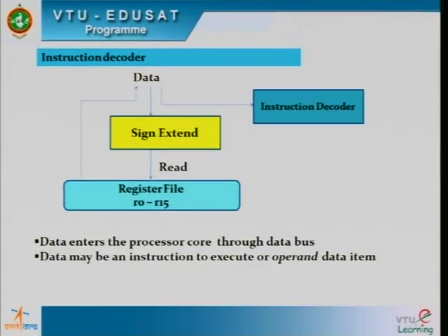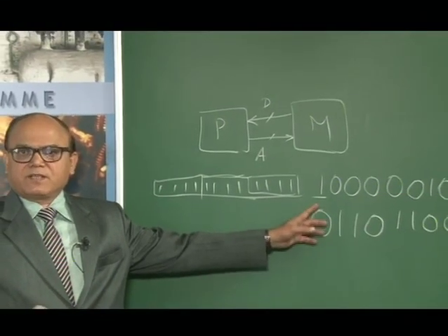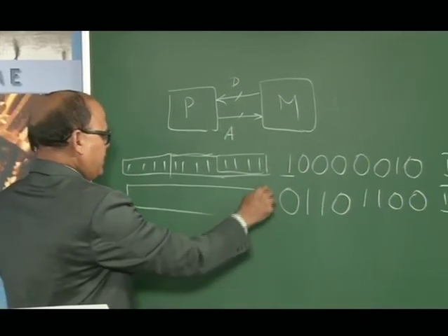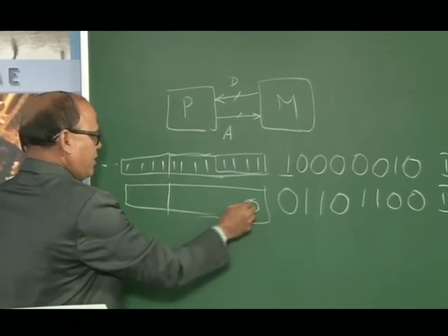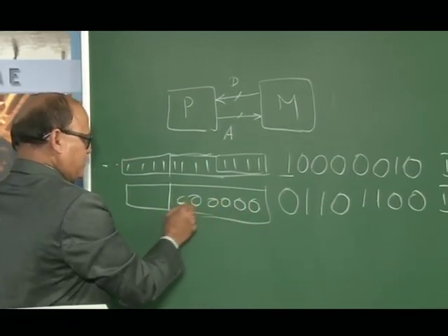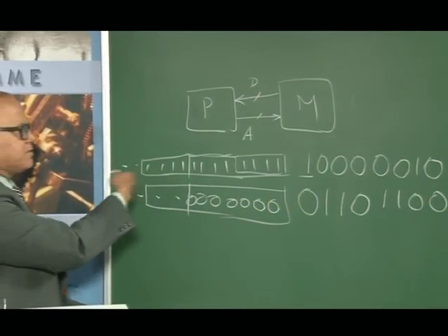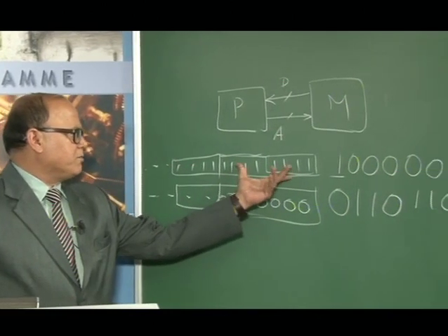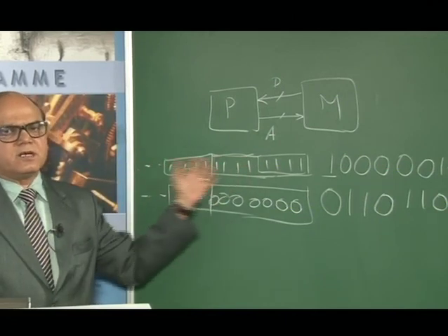If the last bit, the D7 bit of the byte received, is 0, in that case the remaining bytes will copy 000 000 and so on. So it copies only zeros into the subsequent 3 bytes. I have shown only 1 byte here, but the same thing is copied into the remaining 3 bytes.